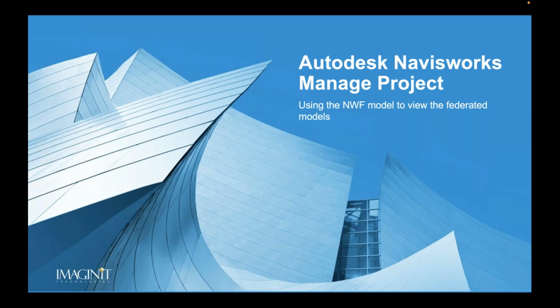And if you know the Navisworks software, it basically allows me to take the various project models that I have that are in different file formats and combine them by creating something called a cache file, an NWC file. That federated model then allows me to see in context each of the models so that I can do my coordination. This is where coordination started for Autodesk. There's different things that we can do now that we'll talk about, but this is the tried and true.